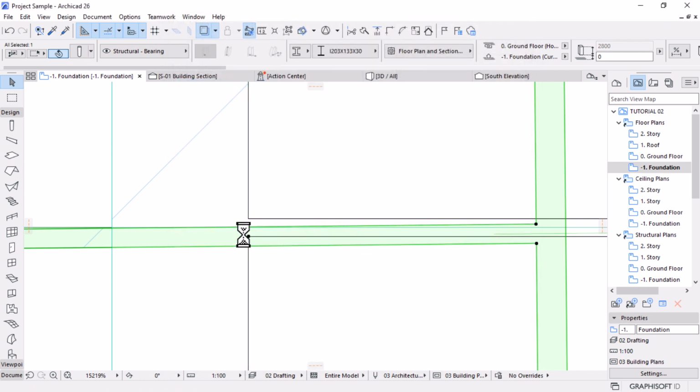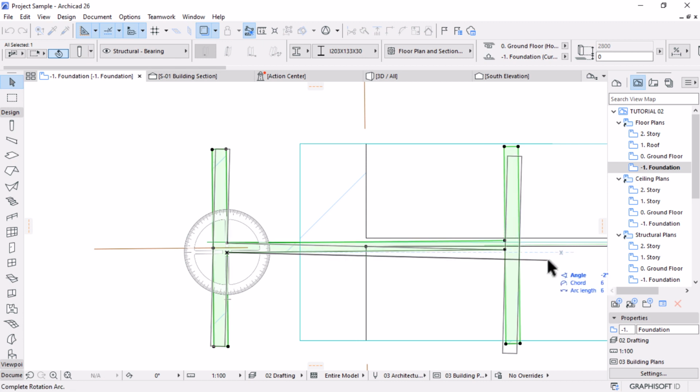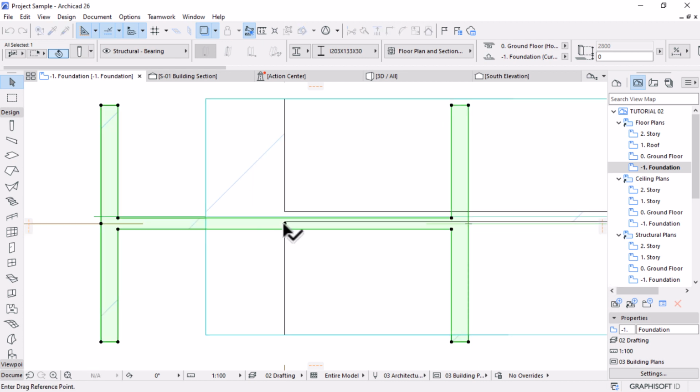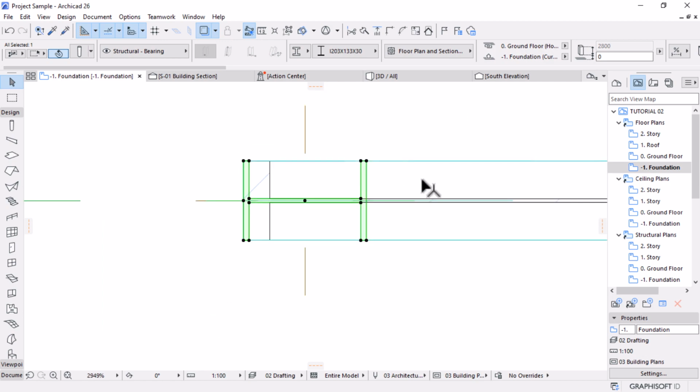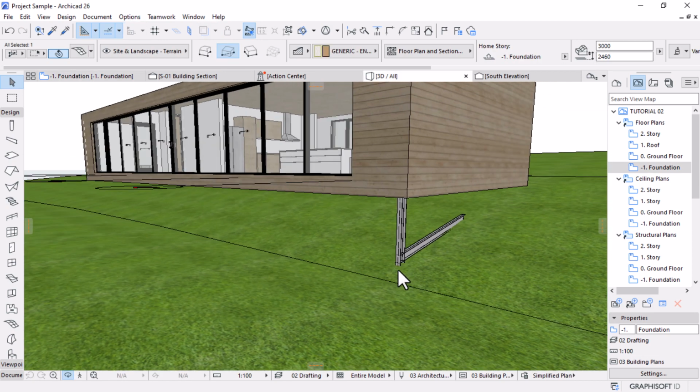Okay, that's fine. Let's just do it manual. I'll pick Control E to rotate, pick this point, and then pick that one. Make sure it's horizontally aligned, and then I can move this point to here. Control D to flash it with the other ones, and then if we check on 3D, that's basically what we have.